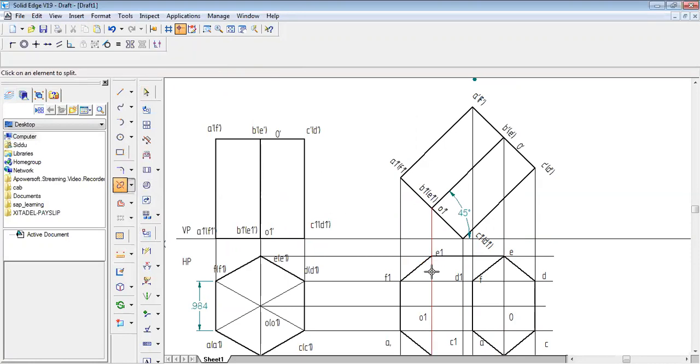So let us connect now. Okay, so A to A1, F to F1 are also going to be seen, and we have connected them with a thick line. Now, again, when I'm looking from the top, the portion which is resting on the wedge, that is C1 to D1, B1 to E1, A1 to F1, is going to be unseen to me because it is farthest from the observer. This surface is going to be covered by this and this, right? So you cannot see it.